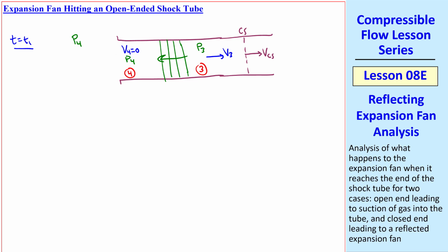This is not as common since we usually have a closed wall here and we pump up the left-hand side of the shock tube. In order for this to happen, you would have to apply a vacuum on the right-hand side of the shock tube so that pressure P4 is greater than the pressure we had called P1 before the shock tube diaphragm was broken. I have not seen this case analyzed in any textbook, though someone may have done it without me being aware.